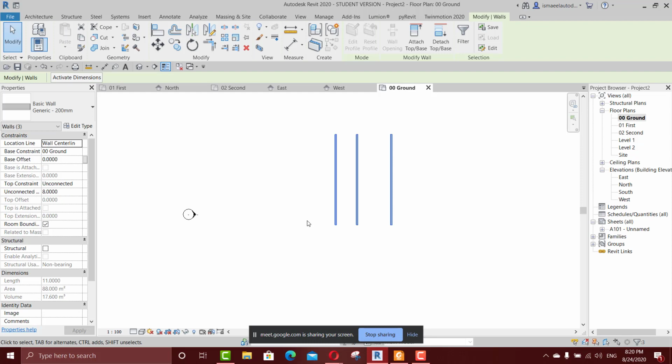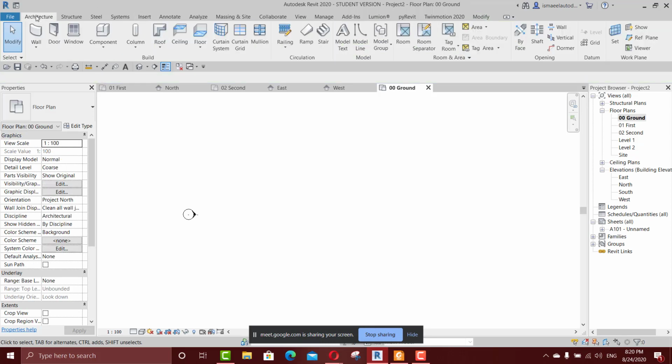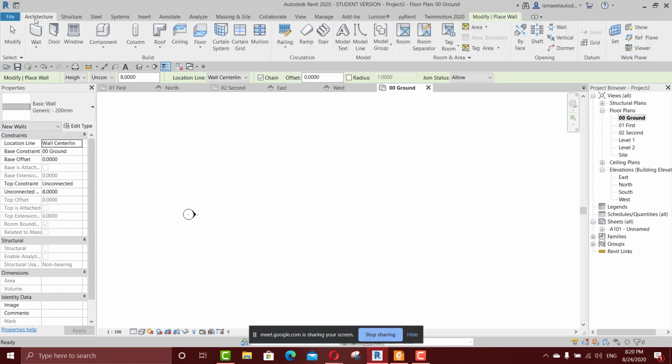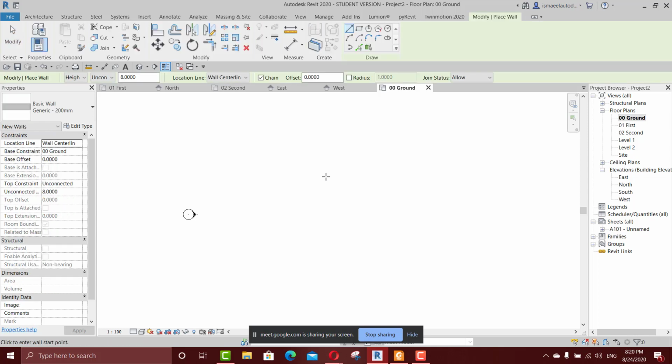For the walls, I did say before we do have it in this architectural tab in this wall panel. Okay, we do have the walls. If I just click it one time, I can directly get in my comment, or I could directly click the shortcut WA. Please, guys, if you repeat this course, or watch it again, please use your shortcuts because it's really important for you.